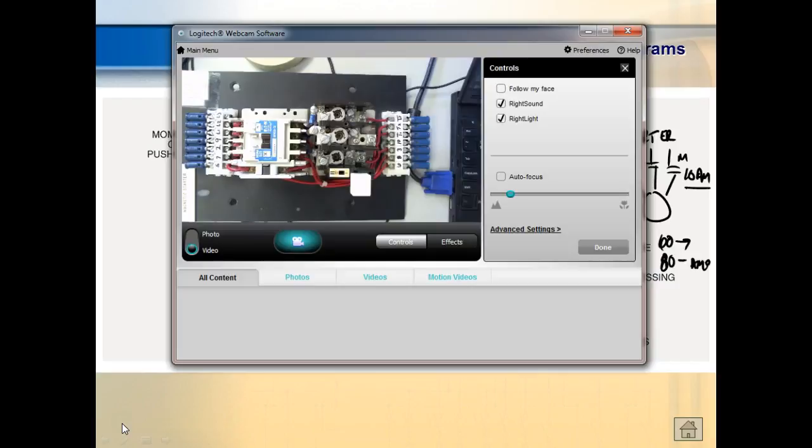Our motors are what we call dual voltage motors, so we can wire them either way. And since the voltage is not set, if you run the motor on low voltage, it's going to pull more current to develop that horsepower, right? You understand? If you run it on a higher voltage, it's going to be less current to produce that horsepower. Of course, it costs the same thing. Y'all understand that?